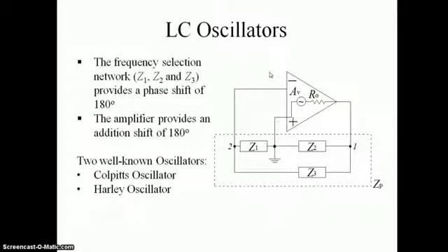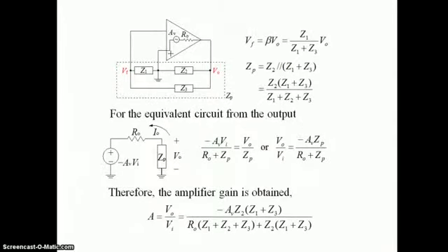The basic principle is the same as the Barkhausen criterion. The whole calculation is done in a similar way. This one is the feedback section, and this is your amplification factor. When the loop has 360 degree or 0 degree phase shift, we finally get the oscillated output in a sustained manner, and the gain A is equal to V output divided by V input.